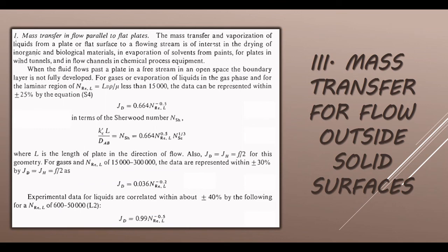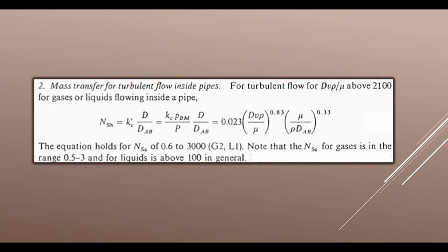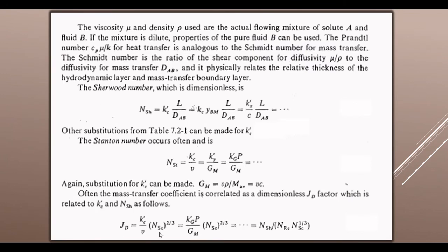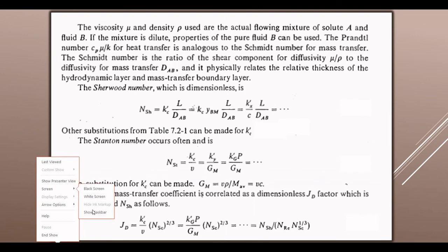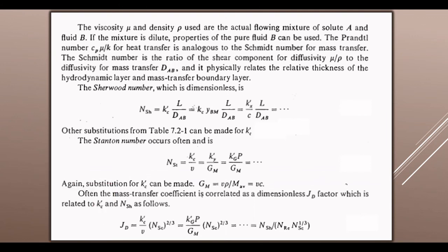So again, I'll go back to that part where we have another expression of the J sub D which is the starting part of this topic, the correlation of the different dimensionless numbers. So knowing that this is the J sub D now, that we will equate to our J sub D based on the geometry of the flat surfaces, we can equate the two values.